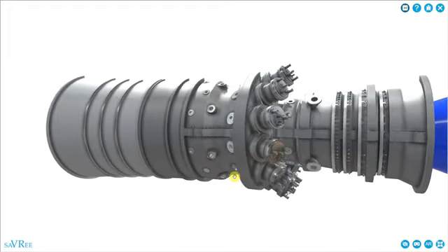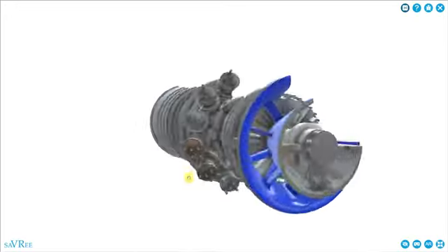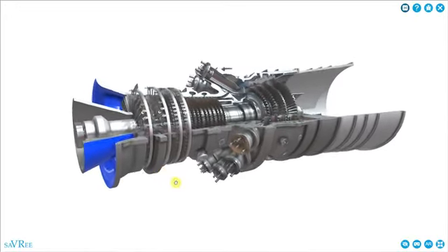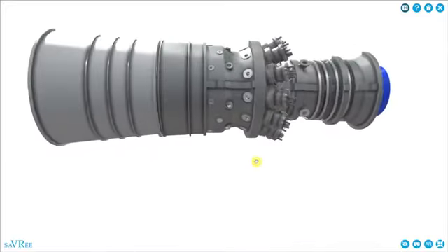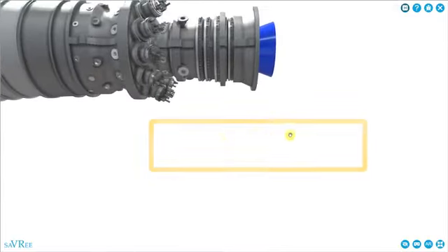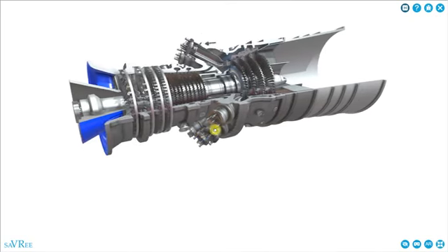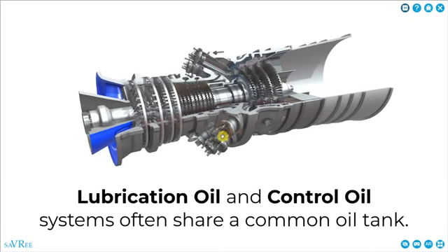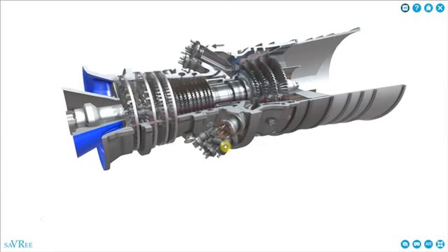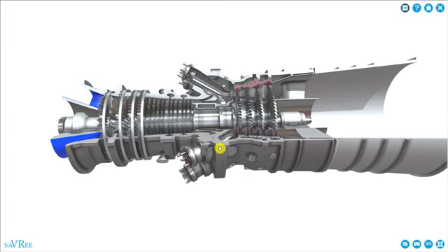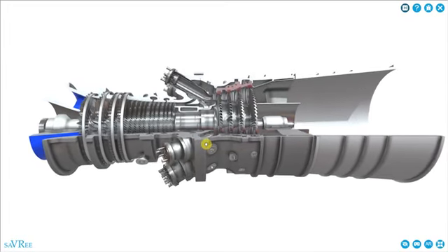It will have a control oil system installed nearby. Quite often the control oil system tank will be mounted directly underneath the turbine. So in this section here where my mouse is, and then we'll have several pumps that we use in order that we can pump the control oil around the system, and we'll use it to actuate valves and move actuation pistons, etc.